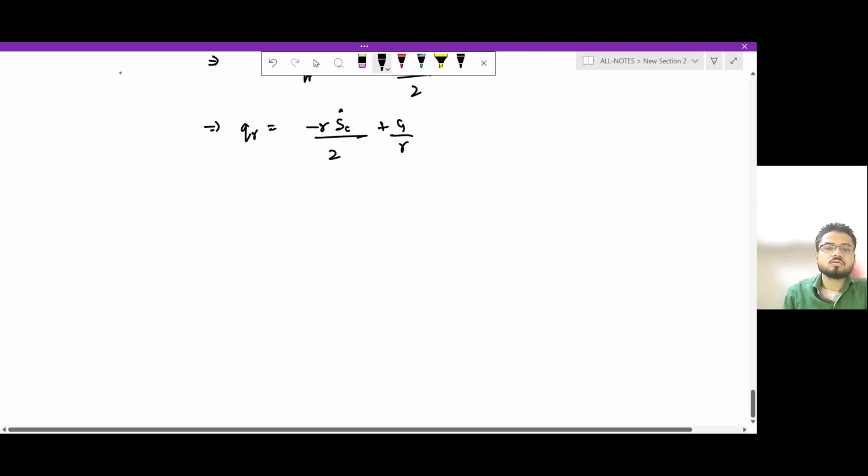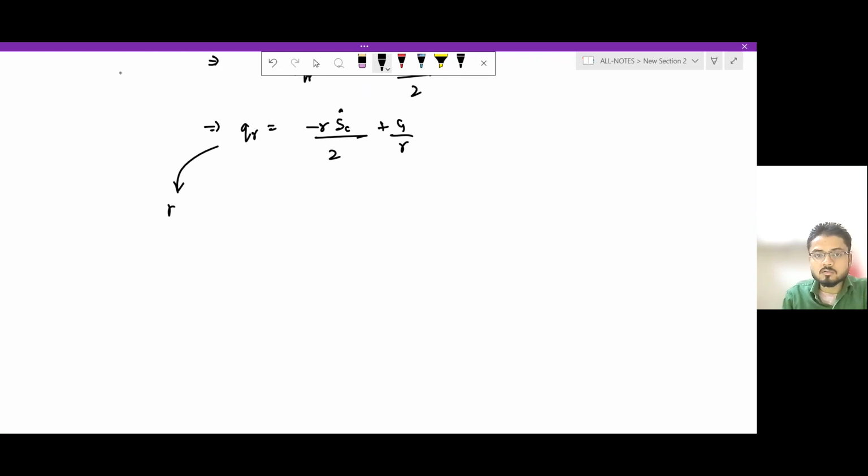Now, we use the identical logic that we used in one of our earlier problems, that Q_r is the heat flux at any certain radius, at any section of this entire wire. So Q_r can never be infinite. An infinite heat flux would mean an infinite energy, which is impossible.